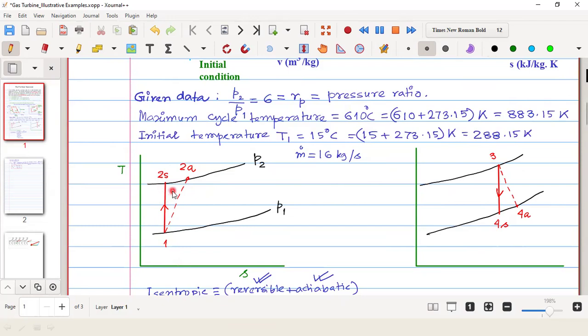But here we have to understand one thing, that the processes are adiabatic. So there is no heat loss. During the friction, there will be heat generation due to the frictional rubbing, so basically entropy increase. Heat loss is not there, and entropy change is always increasing in the system. Otherwise, if there would have been some heat loss due to heat transfer, then we could not conclude whether the entropy will increase or decrease.